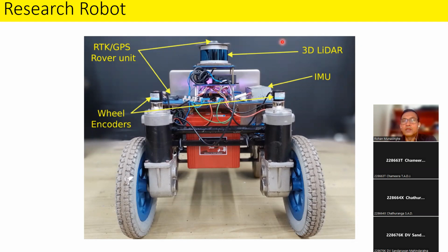In addition to that, you have another sensor, the IMU, inertial measurement unit. This is to figure out your posture, whether the robot is standing upward or slanted to one side or pitching down or up. It tells you about the terrain, how flat or how awkward the position of the robot is, because all of these measurements, particularly the LiDAR, will provide different information if there is a tilt in the robot. Of course, RTK GPS is immune to that. It doesn't know the posture of the robot. Wherever the sensor is, it gives you the GPS position.